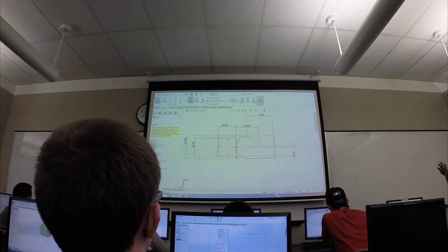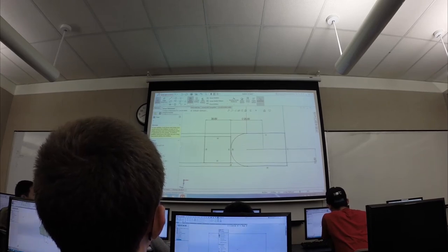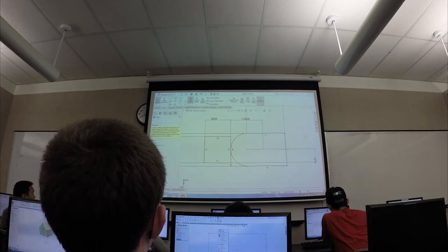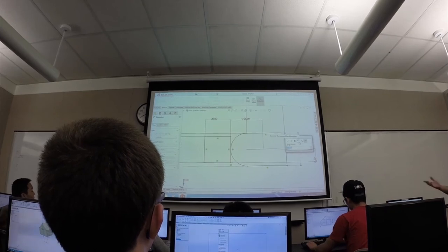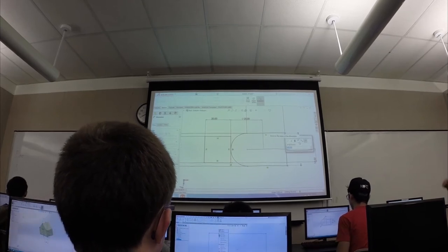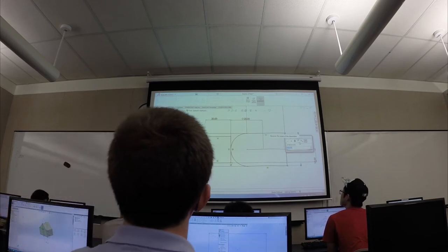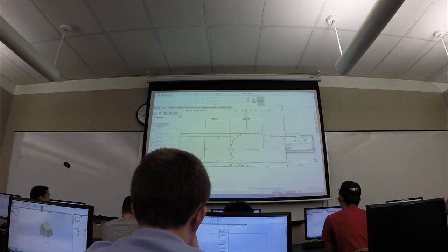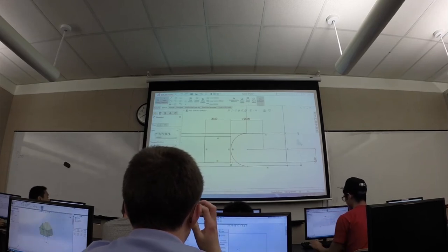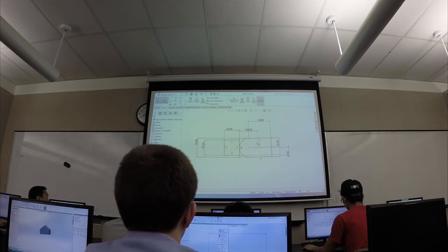So the box is now saying, oh, okay, my vertical dimension is gone. I don't know what size I'm supposed to be anymore. So you would go about just redefining it. Because we set it to 25 previously, the shape doesn't change when the dimension disappears. It retains the size, but you just have to redefine it. So you're going to define the right side of that square right here, and then you notice that the box turns back into a solid black line.